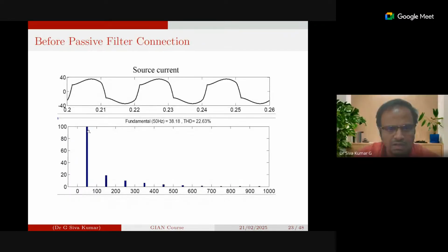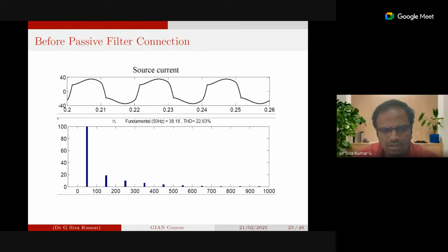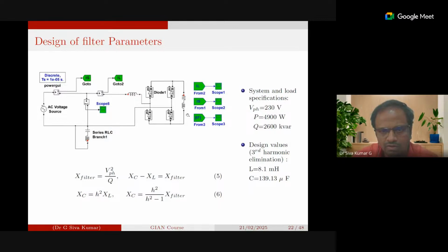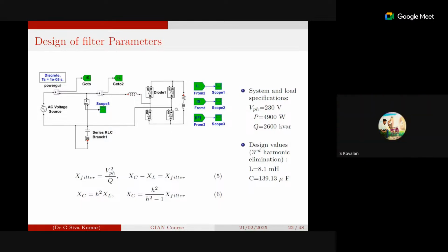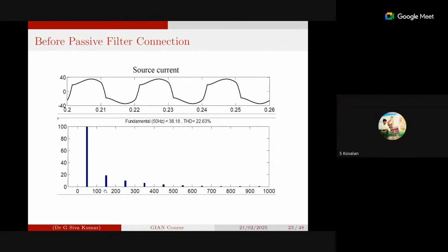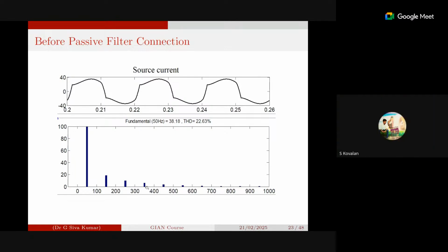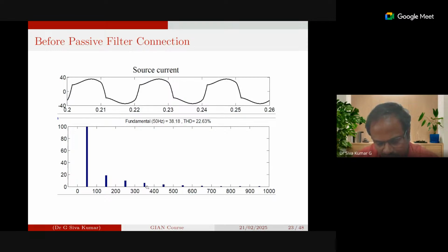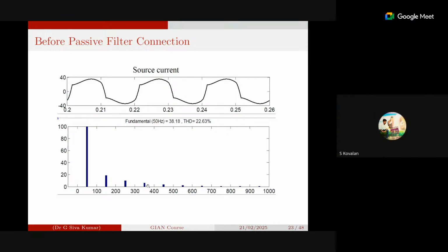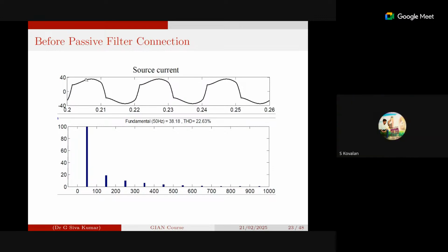in this particular current, you have the frequency components. The load current on the rectifier side, the current drawn from the source, is going to have the first harmonic, the third, the fifth and the seventh harmonic, which the load is going to draw, or in some cases where you show the nonlinear load as a current source, it is going to inject the current harmonics. See this particular frequency component which will be there in your source current.